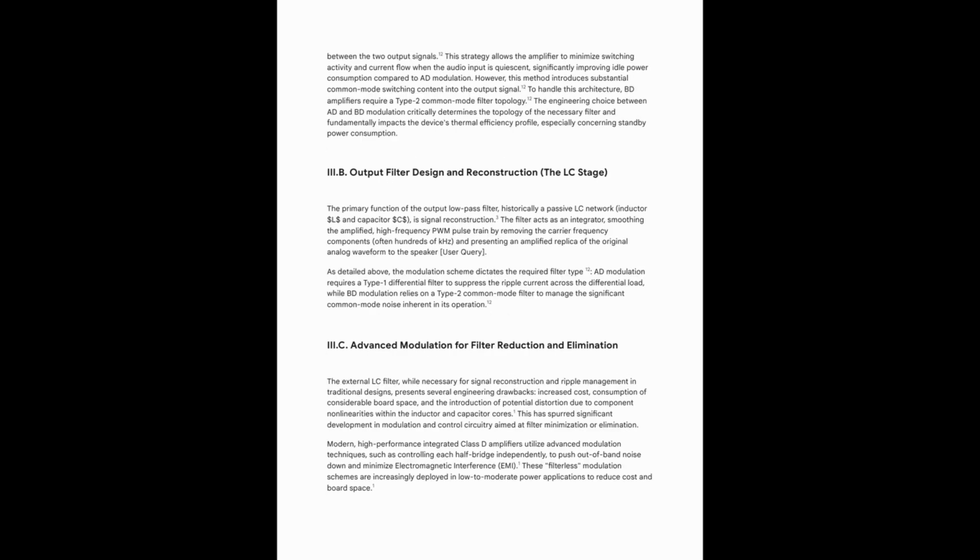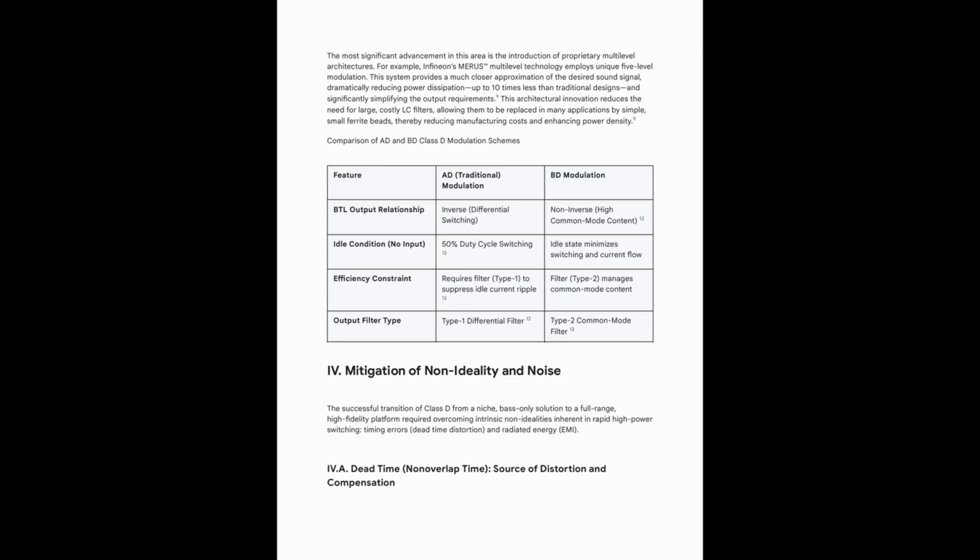And second, and this one's trickier, is switching loss. This depends on how fast you're actually flipping that switch, the switching frequency, f_sw, and also the energy needed to turn the switch on and off, the gate charge, or QG. Right, and here's the conflict I see coming. For really good audio, high-fidelity sound, you need the full range, right? 20 hertz all the way up to 20 kilohertz. Yep, the full human hearing range. To reproduce that cleanly with a switching amp, don't you need to switch really fast? Like hundreds of kilohertz, way above the actual audio frequencies.